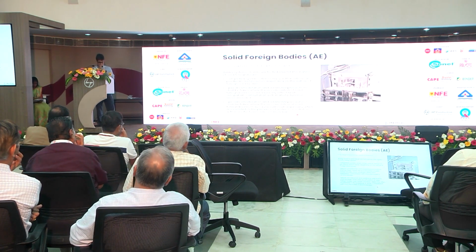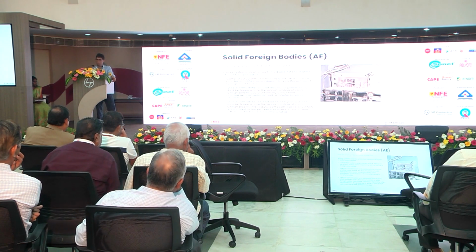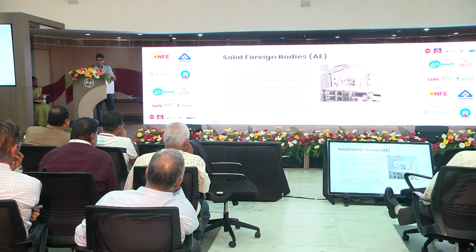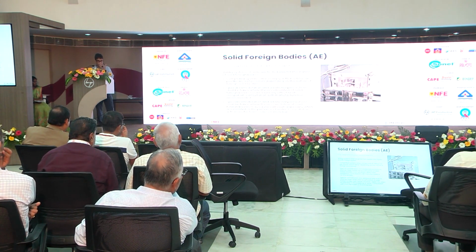So solid foreign bodies. This is again an image. You've got a massive amount of dust that's collected in here. This is going to go to your terminals. The impedances are going to increase, and this is going to cause a problem from a short circuit point of view. If a short circuit happens, your device might not trip.